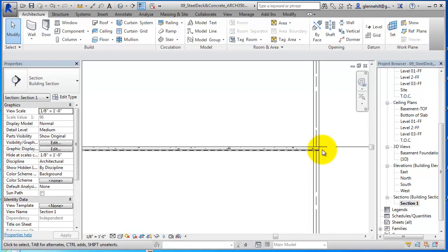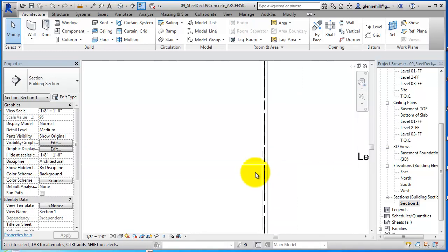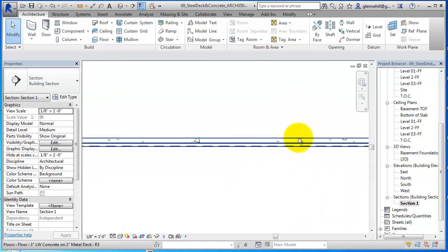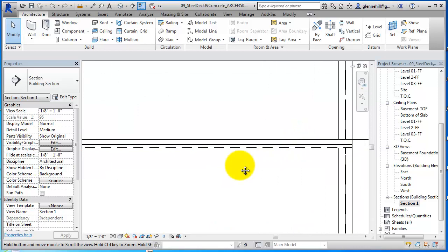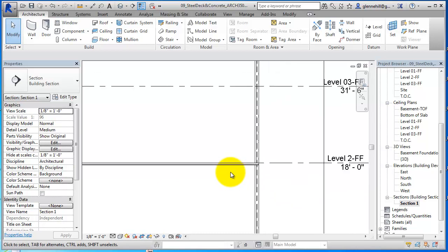And notice also it's located at the finished floor. Okay. Now, since the total of this is 5 inches, we're going to put our beams 5 inches below this, so our beams and our girders, and that's in the next video.